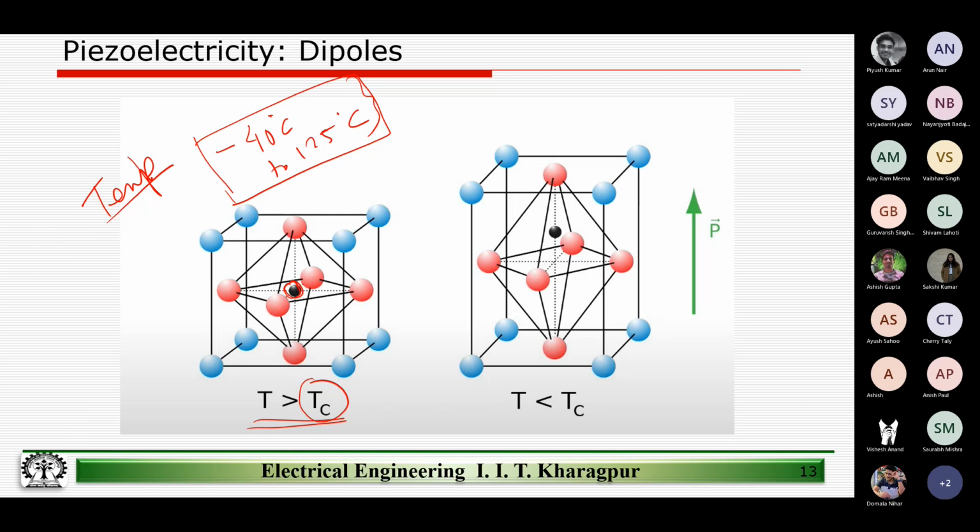So typically what happens is, this is what the second picture is actually saying. When we are developing piezoelectric transducers, these perovskites are taken and heated close to the Curie temperature, or in some websites you will see they heat it actually above the Curie temperature, which can be, let's say, 600 or 700 degrees centigrade. Few places they say they heat it a little bit above the Curie temperature, and then while cooling, a strong electric field is applied, and that is known as the Poling direction.